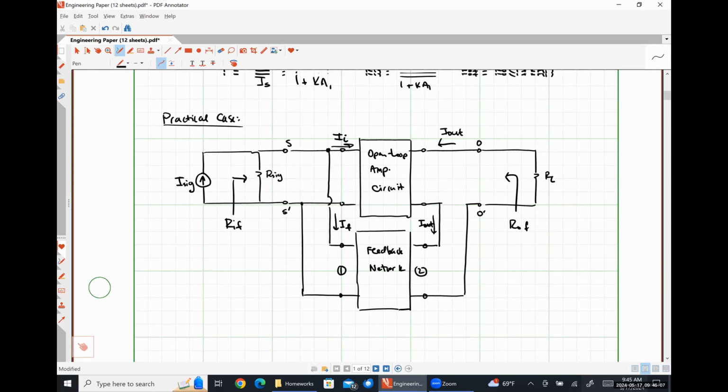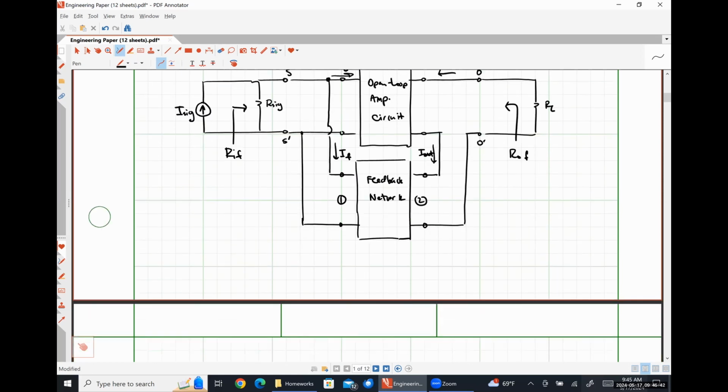And the reason why I'm asking about R22 is specifically because port 2 was connected in parallel to the output terminals of that amplifier. So this is the same process that is going to be used to determine R11 here. When we found R22, and this was finding the loading factor when we had a parallel connection, we left both ports open circuited and looked into the port of interest. So we're going to do the exact same thing here, right?